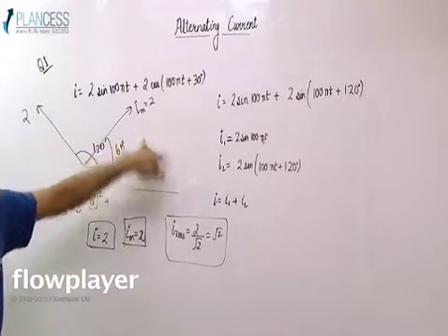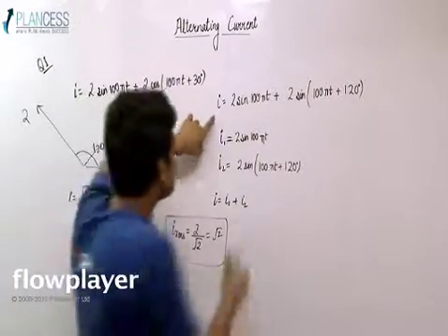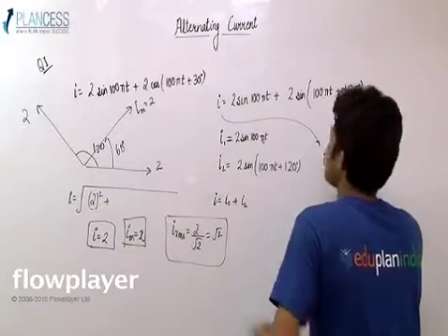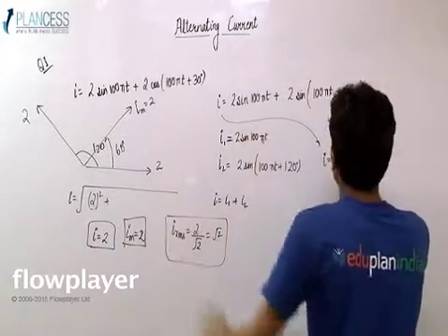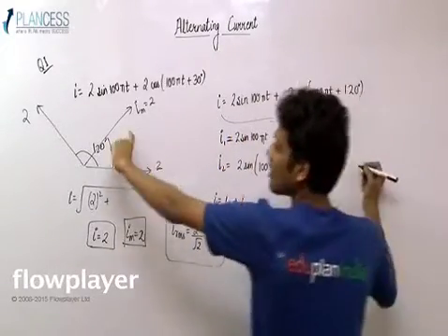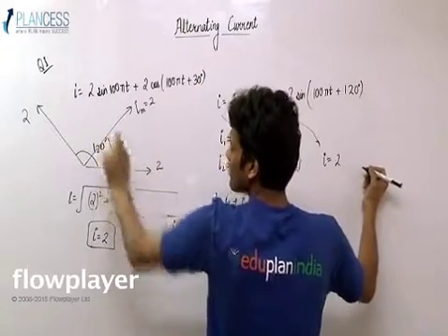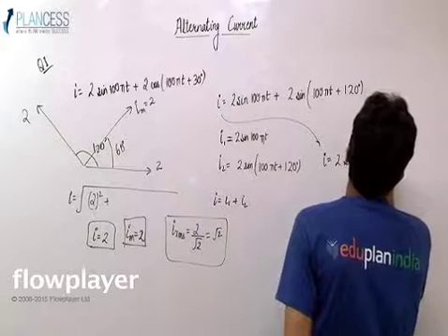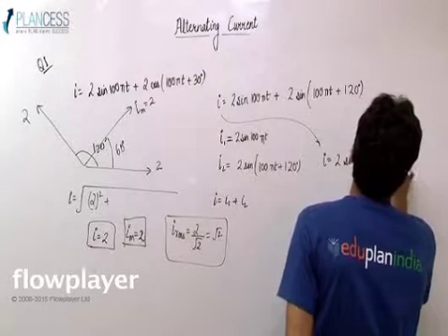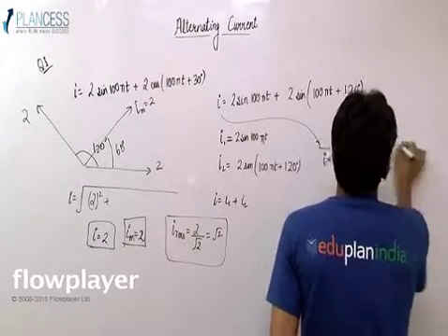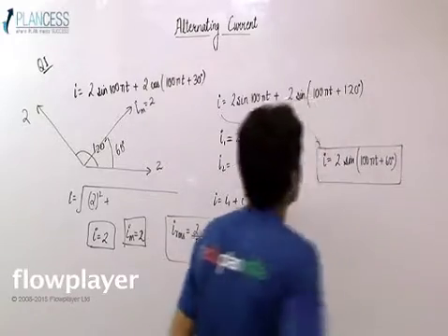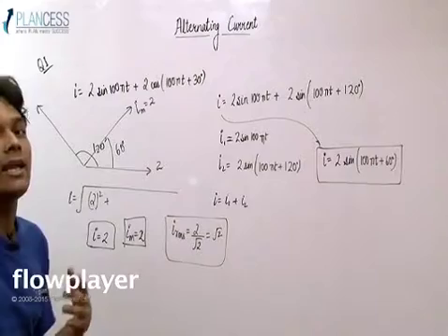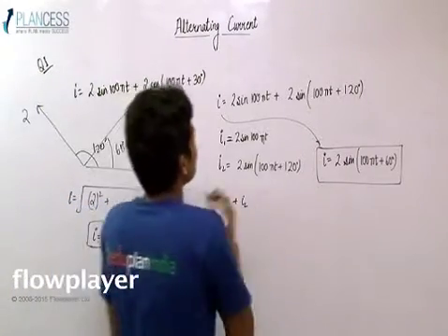So if this IM is 2, I can easily write down this I function now, because I know the maximum value is 2, and it is a phasor at 60 degree. I can say 2 sine 100 pi t plus 60 degree. This would be the I function, which we will get by I1 plus I2. And if you want, I can derive this function also for you.